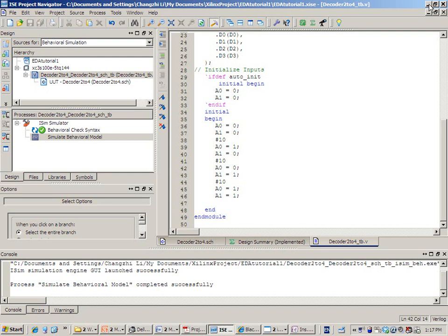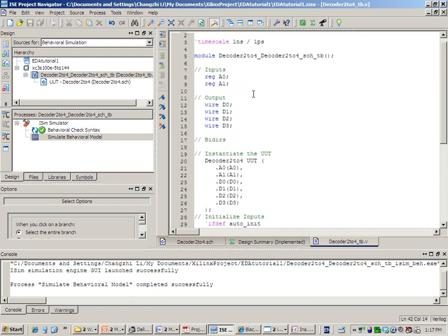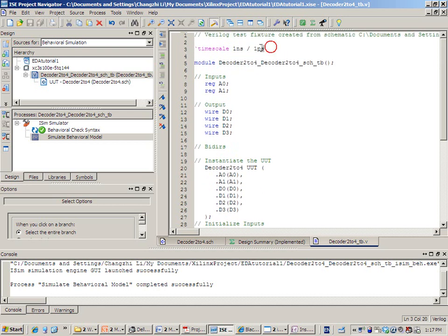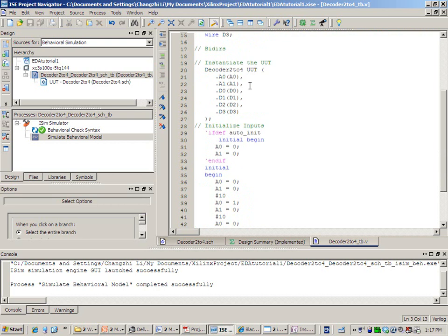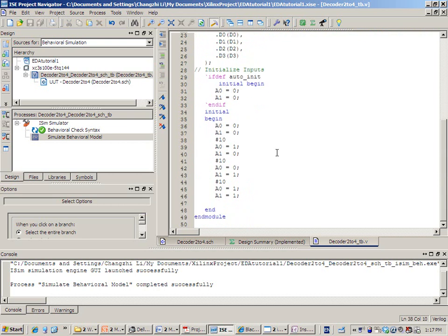Where did you go to change the nanoseconds? On the top side, you can specify the unit. So here the unit is nanosecond, and here is the number sign followed by a number. This number will be the hold time, and in this case, it means hold for 10 nanoseconds. So when you work on the project, you have to change this from 10 to 15.